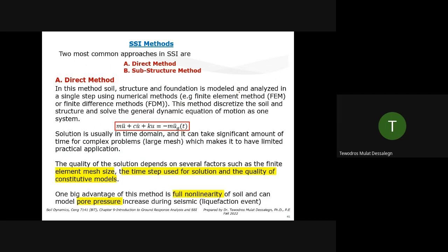SSI methods: the two most common approaches in SSI are the direct method, direct integration. We have a general dynamic equation, the inertial component, if you remember from chapter 2, theory of vibration. Inertial component, the damping component, and the stiffness component. And this is the ground motion, the forcing component. So there are methods using directly integrating this in the soil and in the structure.